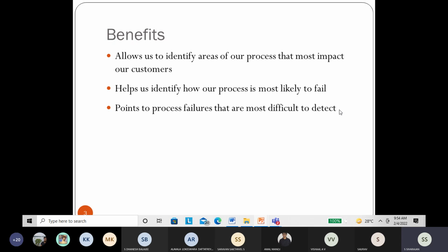In the process, what is a failure mode? And from the failure mode, we are going to know the severity and occurrence, and how we are going to detect it. Three things are important. The first thing is, what is the failure mode? And then for that, we have to find out three important things. One is the severity. Another is whether it is detectable, which is very important: whether we can detect the failure mode properly, whether it is easily detectable or very difficult to detect. And the third one is how frequently it is occurring. These three will decide how to find the risk priority number.